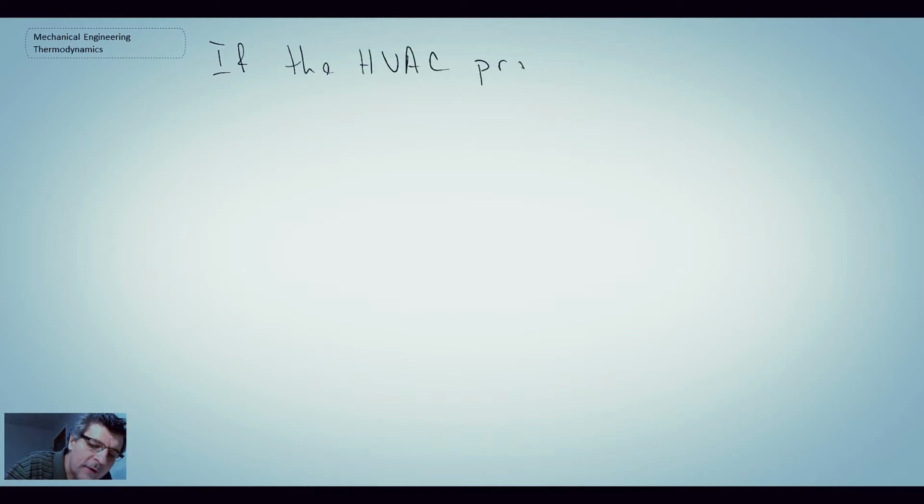Now, we talked about the psychrometric chart last class, or last module, and what we said is that the psychrometric chart is a beautiful shortcut for being able to do these calculations very quickly. However, remember that it only applies if you're dealing with atmospheric air at 1 atmosphere, so 101.325 kPa. If they take place at different pressures, then you need to have a different chart that has been corrected for your elevation, or you need to use the equations that we looked at earlier.